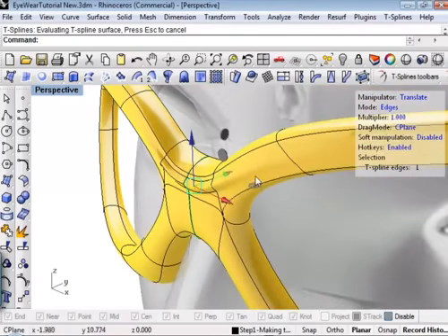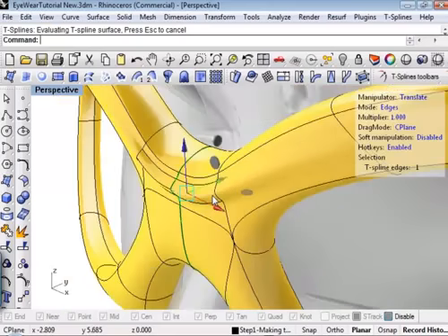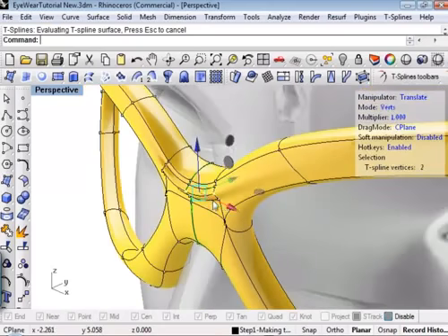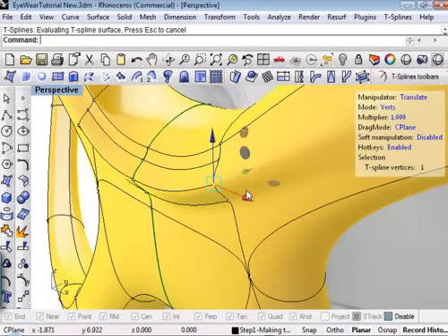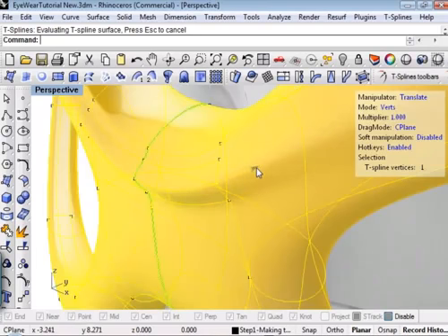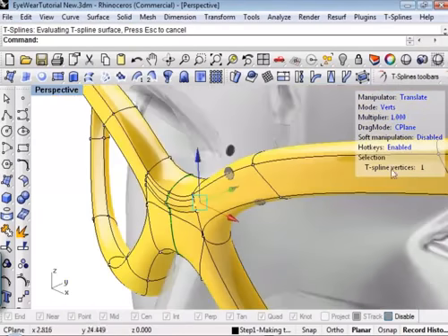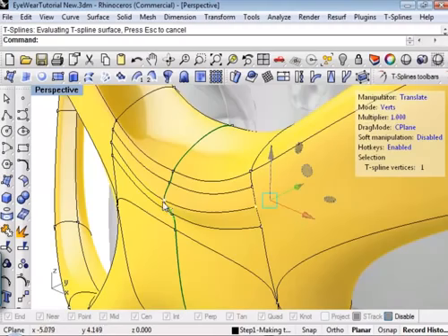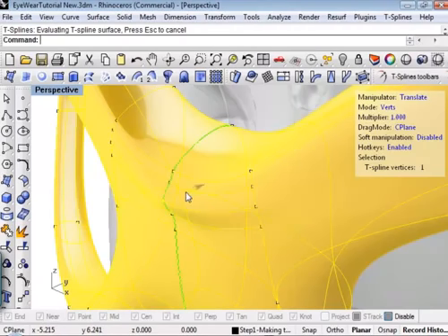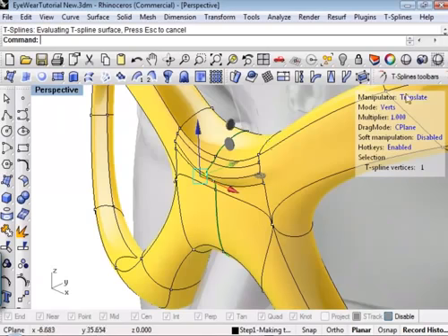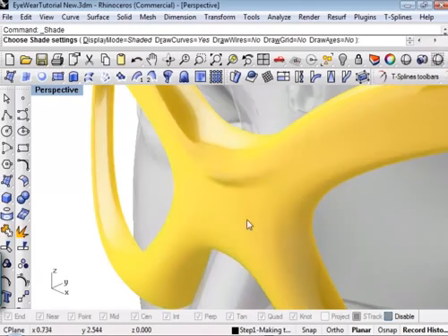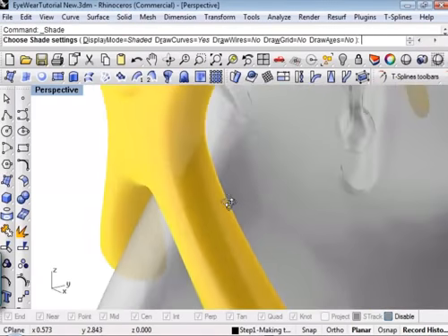And I can control how sharp that is by going into my vert level. I can pick this vert and I can have it die out faster than a crease. So I can really isolate that detail, whereas a crease has to have two faces. This I can isolate to be just where I want. So depending on the effect you want, that's the difference between using a crease versus inserting an edge.